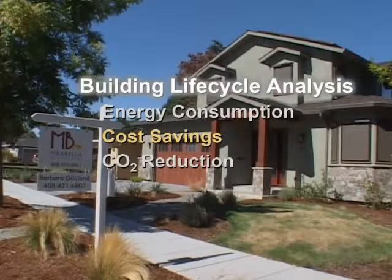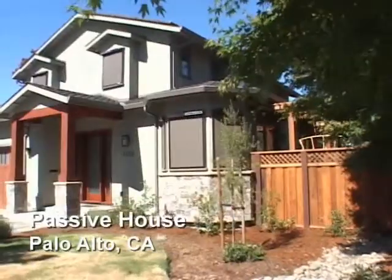Doing life cycle analysis on cost is different than doing it on energy. Passive house and the conventional house will be roughly the same in monthly payments. The mortgage payment will be higher for the passive house, while the utility bills will be lower, and it'll be roughly a wash. But that's for the first 30 years. After that, suddenly there's a huge bonus because you paid off the mortgage, but if you have high utility bills, you don't see much savings. With the passive house, you'll see savings which over the lifetime will add up to tens of thousands of dollars.